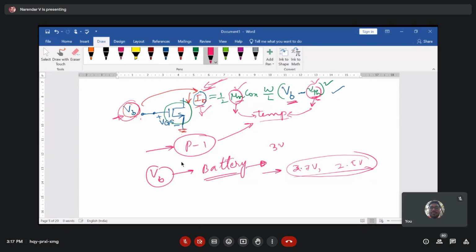Okay, so in the case of multiple current sources, what we normally do is take a single battery. How do we provide the biasing for it? We provide the biasing for all the different VB values. Somewhere you require VB1, and another place you require VB2, because you require ID1, ID2, ID3, ID5, and hundreds of IDs, and as a result you require hundreds of VBs.